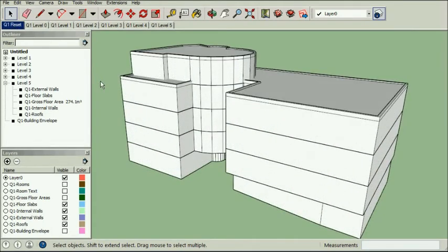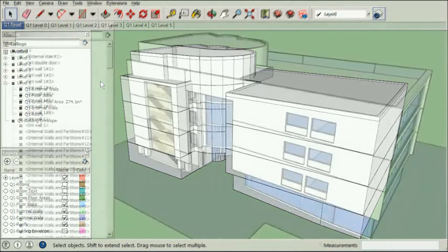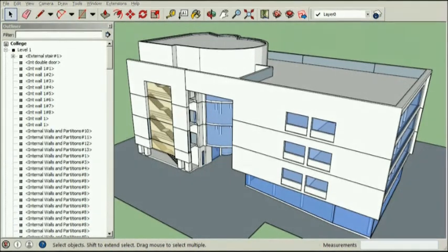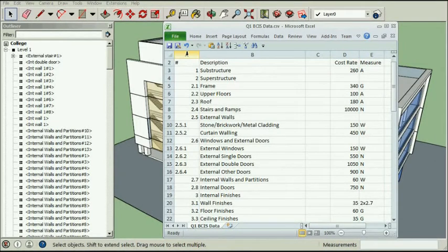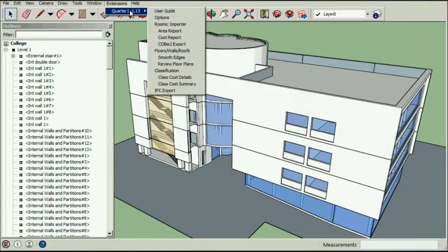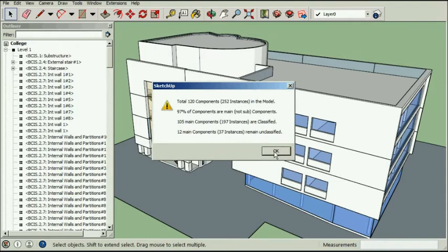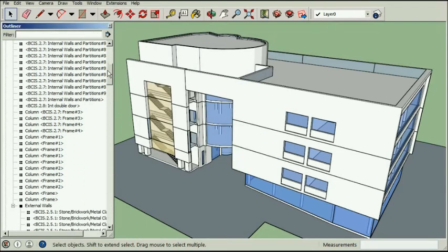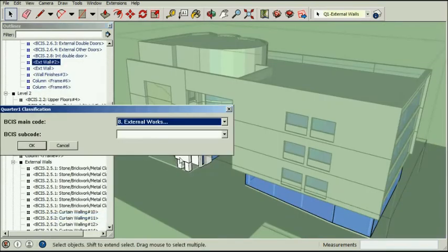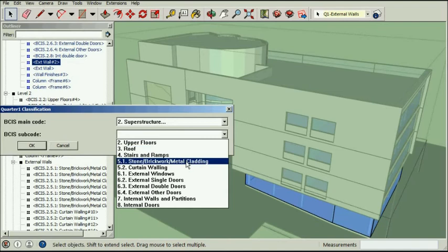Of course, a more detailed SketchUp model representation is always required, even at a concept stage. I'm just wondering, but could another wee file define a classification system? You know, code, description, rate and a method of measurement. If I had named my components appropriately, then wouldn't it be possible for a function to automatically match component names with classification codes? Of course, I can't guarantee that all my component names are helpful, so I would also need an option to manually assign a classification.